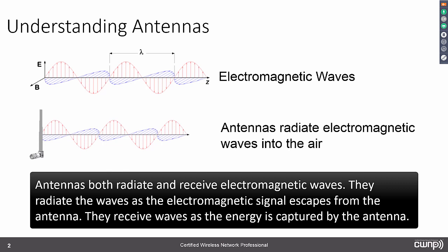And so the intentional radiator can be said to be everything up to but not including the antenna. So if you have cables, if you have amplifiers, things like that in chain from your AP or bridge to the antenna, everything up to the point where the antenna is connected is the intentional radiator. In other words, it's a device that is intentionally radiating energy. The EIRP is the actual radiated strength or power coming out of that antenna.